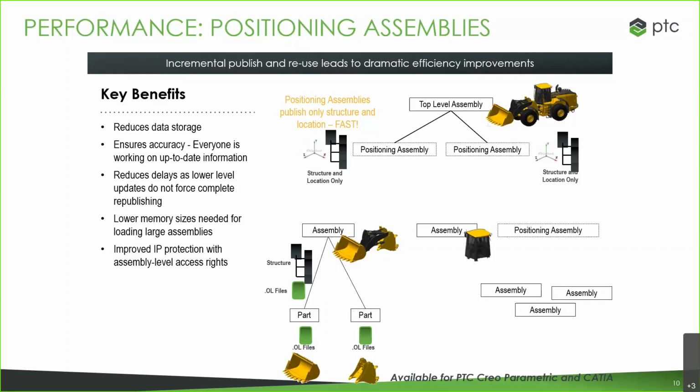And if you create a Creo View file for various assemblies, maybe you're just getting, okay, this is going to show me where this goes, and that's the information that I need, leaving out some of the other information like the specific build tree that you wouldn't need, or you would need in the native tool, but as a viewer is not necessary. So as a result, it's a lot smaller file size, a lot easier to open these larger assemblies.